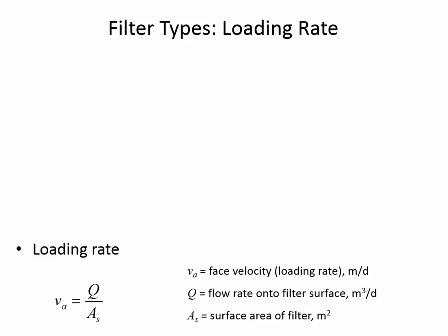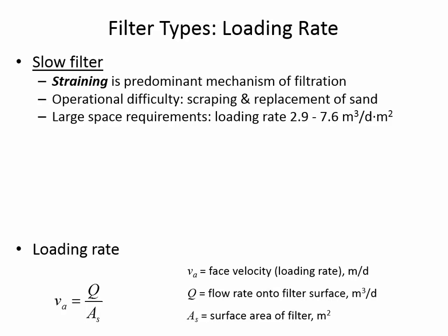Okay, here's sort of the design process, or the sizing process. There's something known as the loading rate, and this is very similar to what we were doing with the clarifier. When we had a surface area of the clarifier, the loading rate there was just the process flow rate Q divided by the bottom surface area of the clarifier. It's the same thing here with the sand filter.